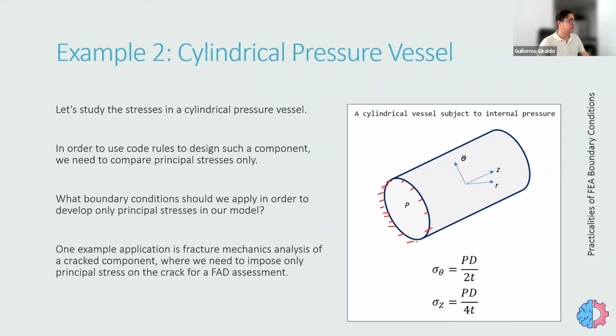So what happens in this case is that, okay, I'm constraining the rigid body motions, but I am also constraining the pipe from growing radially, so it cannot anymore grow in this direction, right? Because this phase or this line is completely fixed, and this growth cannot happen. So what will happen, say if we leave this end free, is that the pipe here doesn't grow, but it tries to go radially, and we get something like that.